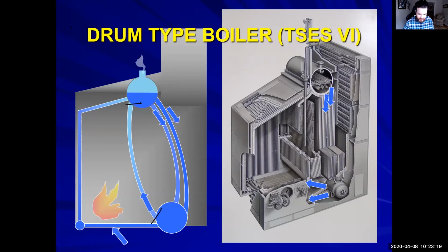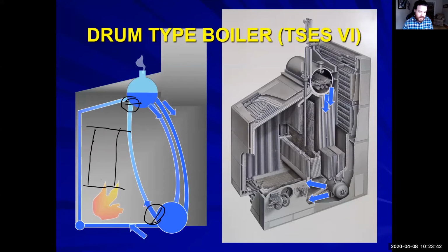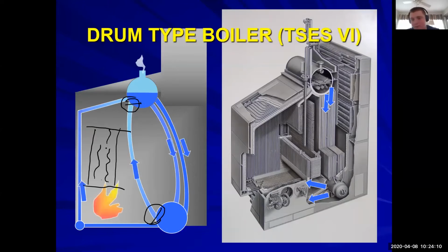And that's the biggest thing you guys have to recognize with this. With boilers and everything that goes with it, you don't know exactly where the point is where it turns into steam. Inside of these generating tubes, you will have basically a column of water that's really hot. But you're going to have steam bubbles, and they're going to be going up. What is steam different from water? What makes it different? Not only just its state, but what about its energy? Much higher energy, due to temperature.